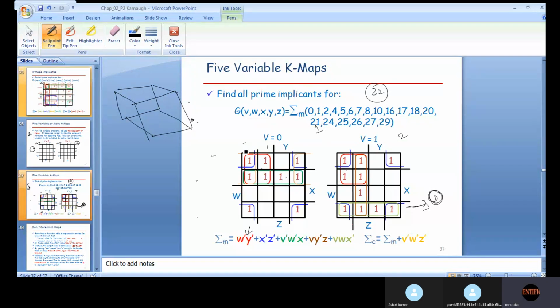Okay, so corners: this is the first K map and this is the second K map. These corners and these corners, you can call all of these adjacent cells. And if you have 4 ones in this corner, and 4 ones in this cell as well, combining these adjacent ones, the 8 you can map as one product term.